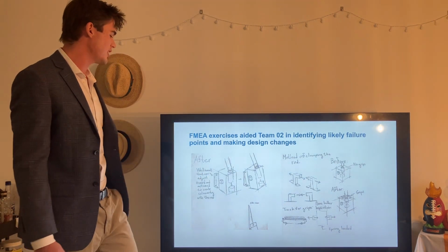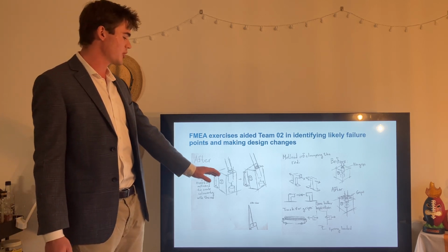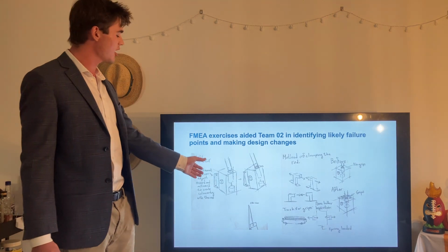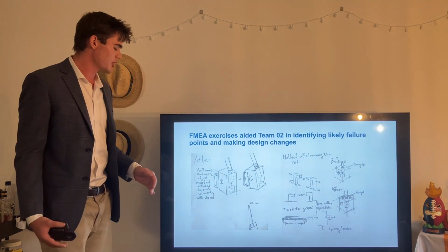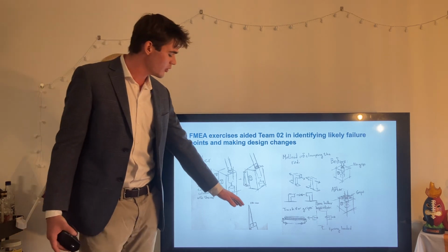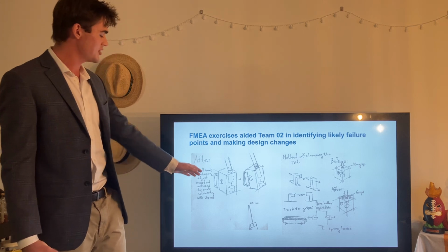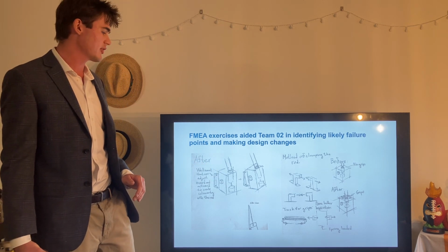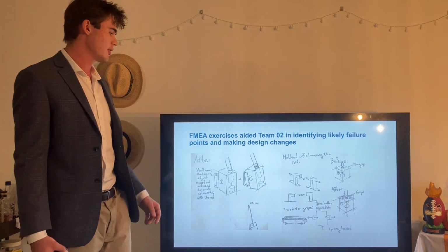The first key failure point was that our wall mount would be at an angle from the twist rod due to the twist rod being very close to the wall, but the device itself having to stick off a few inches of the wall. Our solution to this was creating a headlamp-style twist system which allows the mounting box to be mounted at an angle to the wall so that the twist rod can better connect without putting a shear stress or a bending moment on the twist rod.